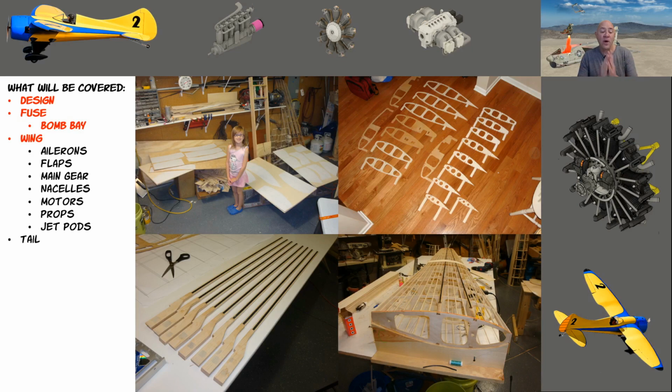But one of the problems I didn't think about using carbon fiber, I know carbon fiber is the strongest when it's in tension. And on spars, it's great, but you've got to think the bottom spar when it's sitting on the ground, that's in compression. So I had a little bit of a sagging problem with my wing. It flexed a little bit too much, wing 1.0, and my flaps were going to jam. So I had gotten around that, but then when I got the landing gear and they wouldn't fit, I just redesigned a whole new wing.